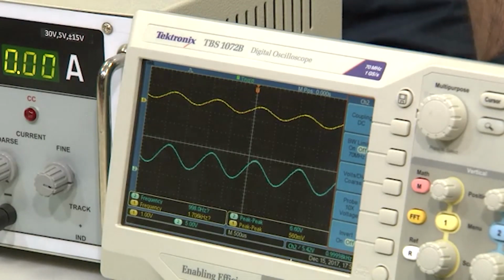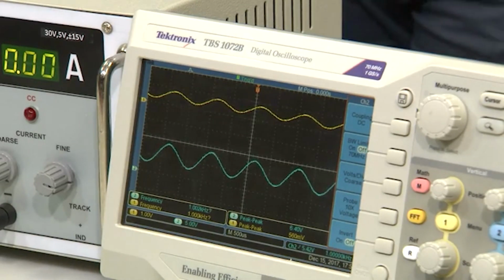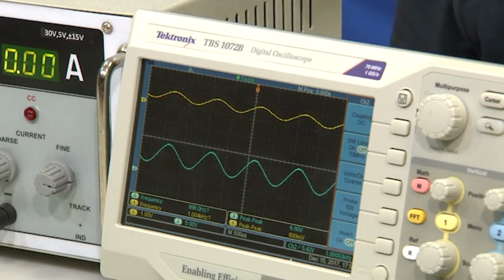So why is there a change? We calculated about 5.5 volts should be the output, but when we see in the oscilloscope we find that it is around 6 volts, right. That is because of the resistor values that we are using, the 10 kilo ohm and 1 kilo ohm. It may not be exactly 10 kilo ohm or 1 kilo ohm, and even a change of few ohms will change the gain, right. So, it is extremely important when we use the circuit that you measure the resistance of the resistor, and then you understand theoretical and experimental calculations.